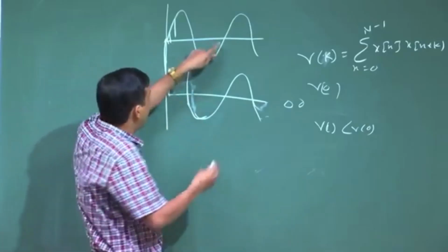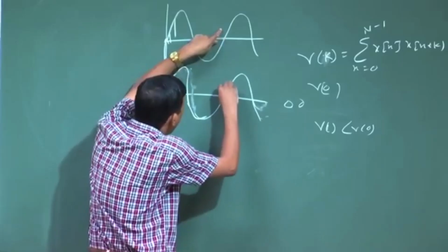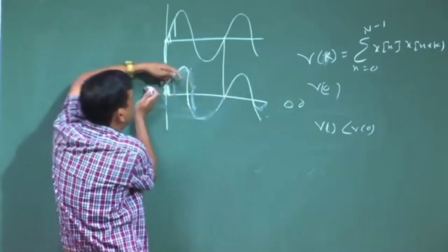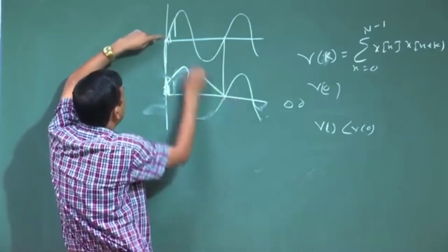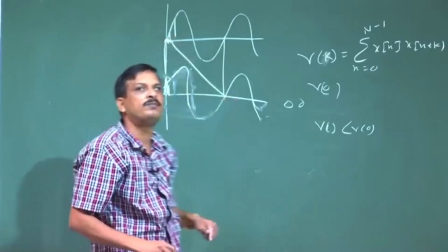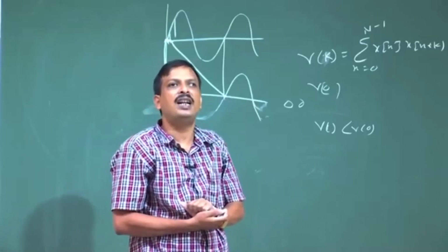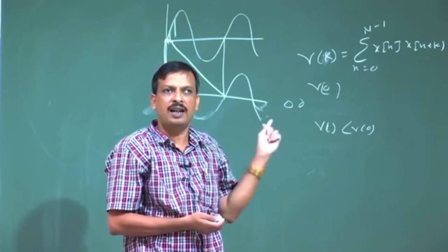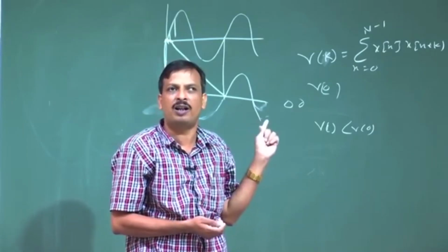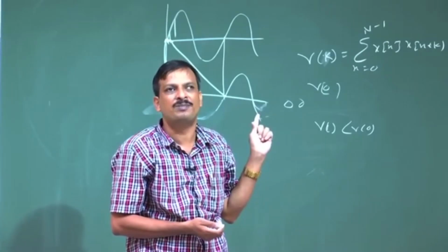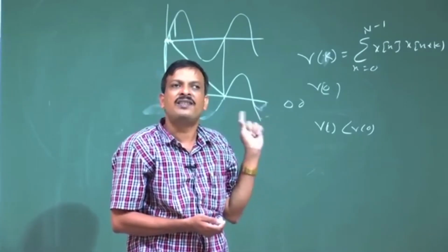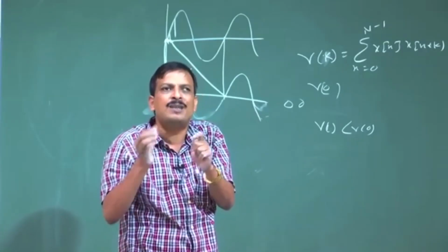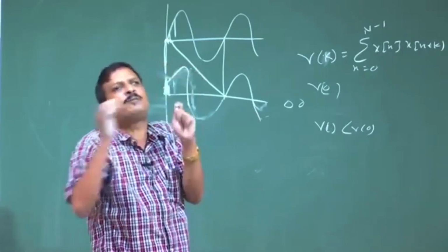If you see, the signal will come in phase when it reaches here. So, if this much shift is there, then the 0th sample will be multiplied with the 0th sample. Again I get the maximum R value. Yes, I get the F0 by 2 also as a maximum R value, because it is a pure sine wave. If it is not a pure sine wave, then I will get maxima when the sample is matched exactly with its period.